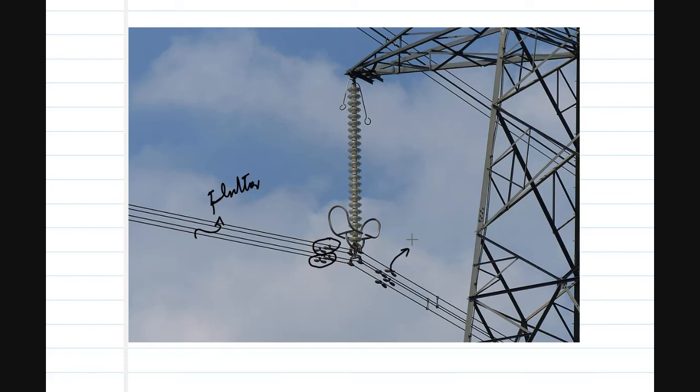These are tuned mass damper vibration absorbers. If there is any vibration in the cable because of the wind, these small masses, or absorbers, tuned to a certain frequency, absorb the vibration from the cable and do not allow it to vibrate. That is the main application of tuned mass dampers.